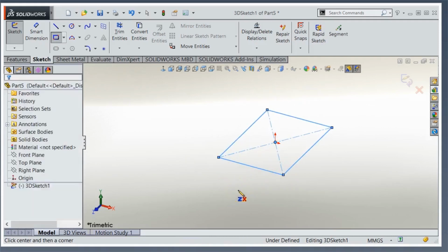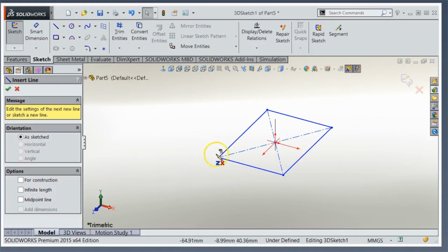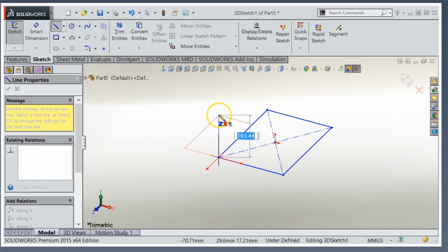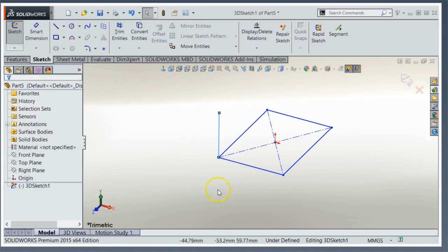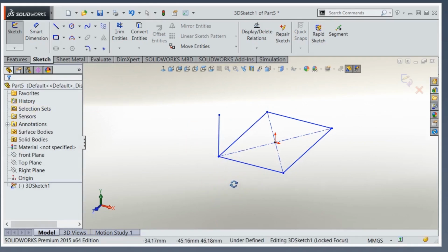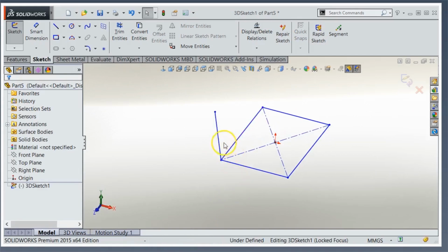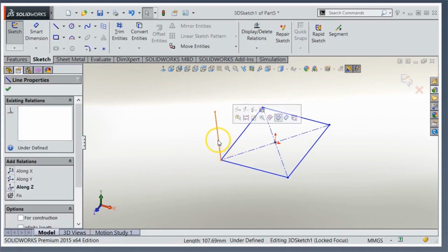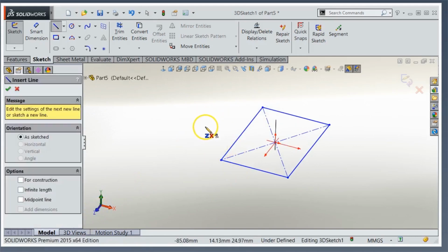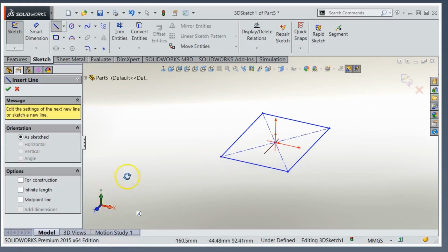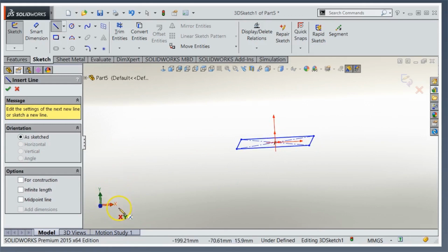So I'm going to go ahead and draw the rectangle like so. I'm going to draw a few more lines as well, so vertical members for the frame. Now this first one here, I'm going to draw it, and I'm going to rotate it. If you notice, it's not vertical. That's because I was still in that ZX orientation. If I hit Tab, that'll change me to my XY, which is vertical, if you're looking at it this way. So XY.